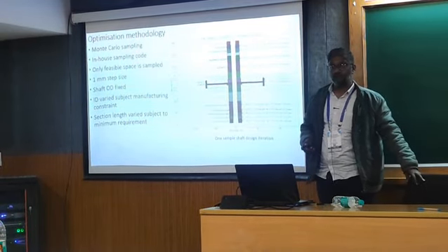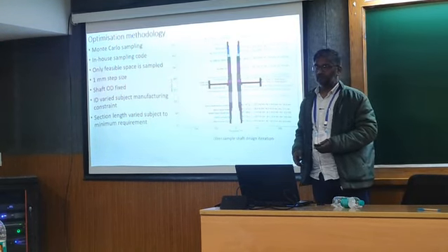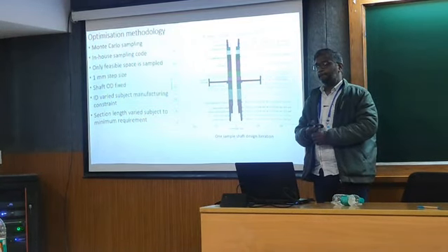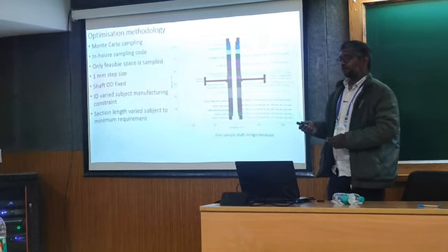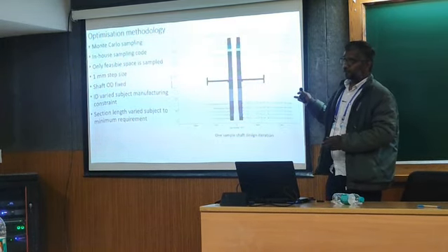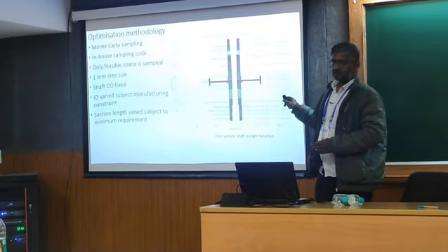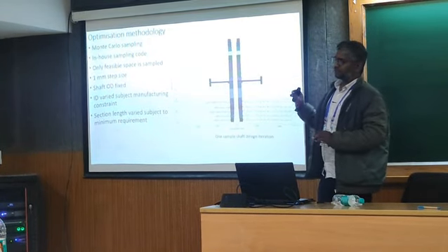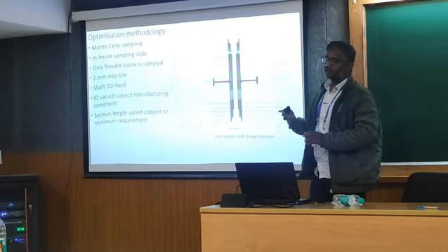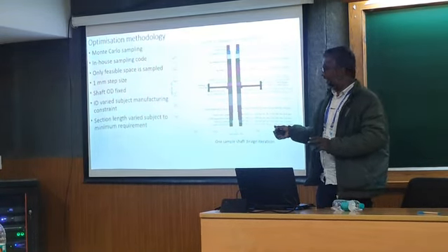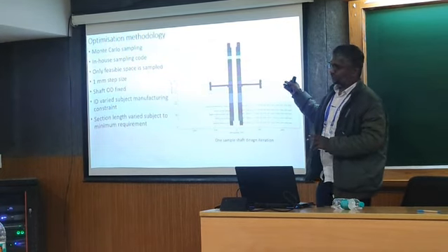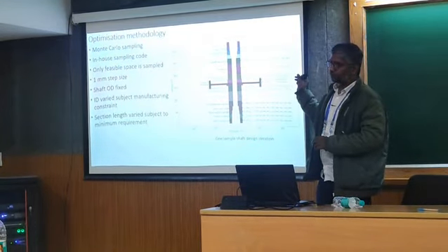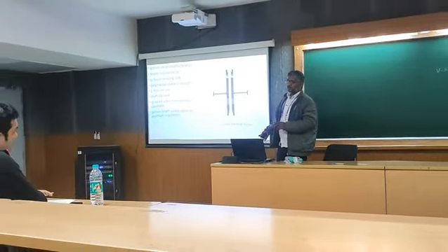Any other questions, sir? What is the total energy required for powering the AMB? We have not calculated. This is a ground-based rig, but thumb rule is AMB uses 1/3 of the energy consumption of the equivalent load supporting journal bearing, oil lubricated journal bearing. Power consumption, including the electric power consumed by the controller and the actuator, is 1/3 of the journal bearing. So it is always advantageous from energy point of view to go to a magnetic bearing, provided the initial cost is absorbed.